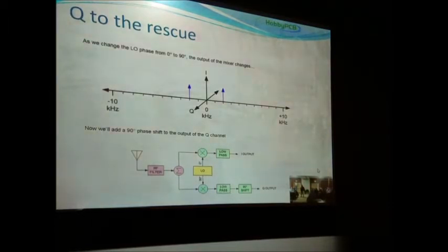The Asus Sonar and the Creative Labs X5s can have up to 114 dB of dynamic range, and they're just $100 devices. So the reason for using this sort of topology of bringing the signal down to where it can be handled by audio processors is to take advantage of that little niche in technology that makes really high performance radios at a really low cost.